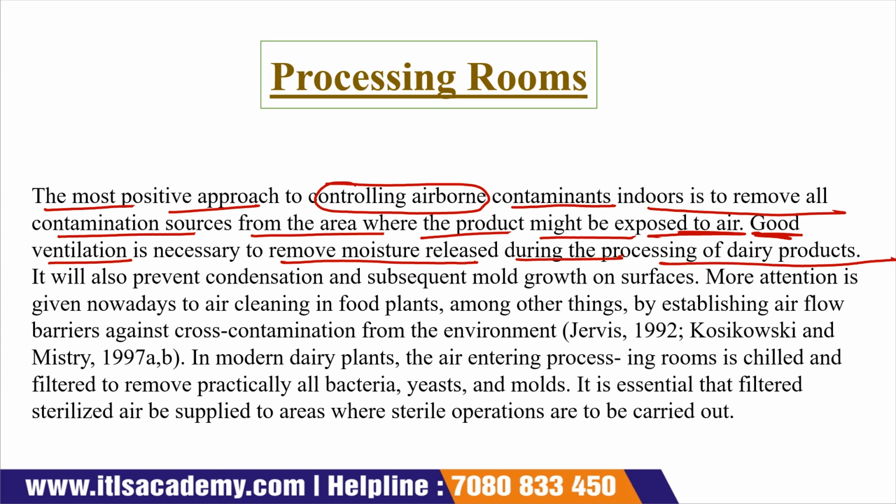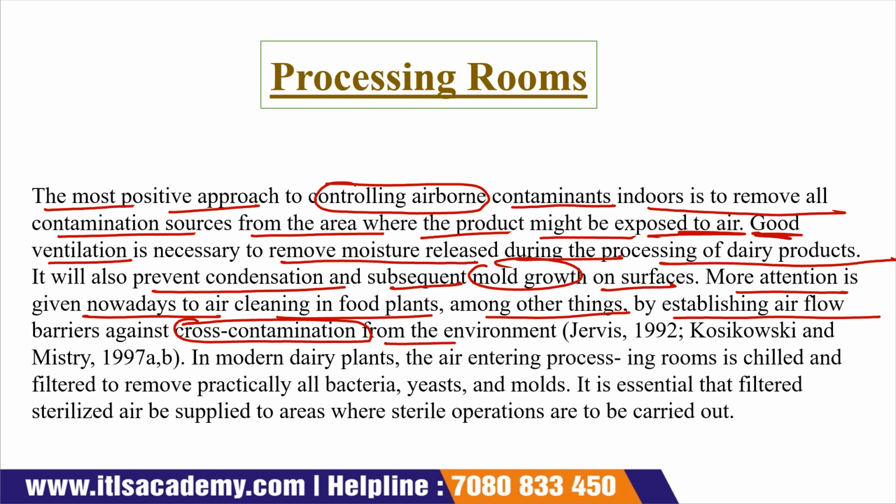It will also prevent condensation and subsequent mold growth on the surface. More attention is given nowadays to air cleaning in food plants, among other things, by establishing airflow barriers against cross contamination from the environment. In modern dairy plants, the air entering the processing room is chilled and filtered to remove particularly airborne bacteria, yeast and mold.